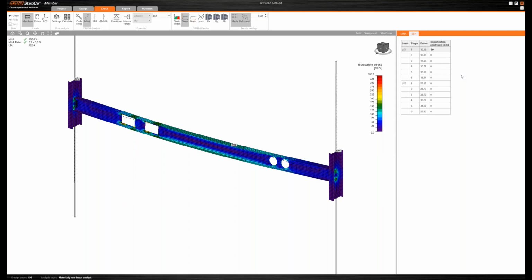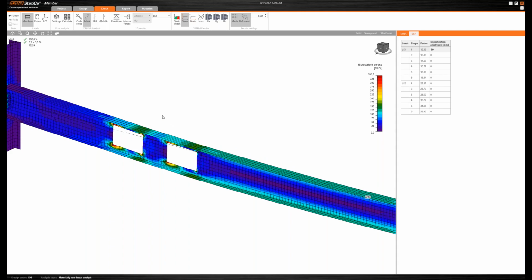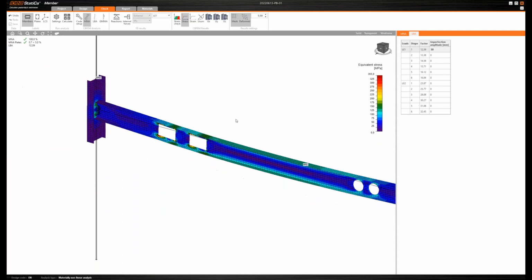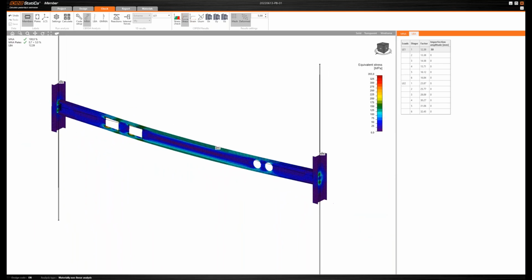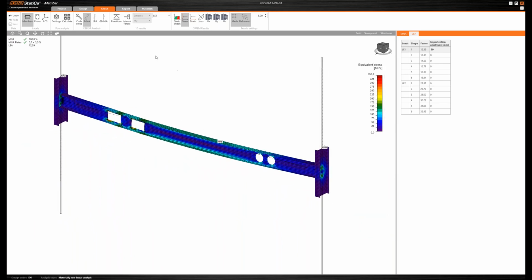Okay. How can I apply a moment to the castellated beam? You can apply a moment by, this will be a triangular load, let's say. I'm not sure how you want to apply it, but since we have a shell element model, a moment will be a triangular load.